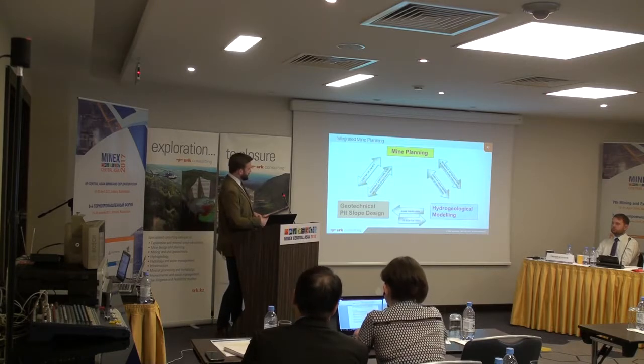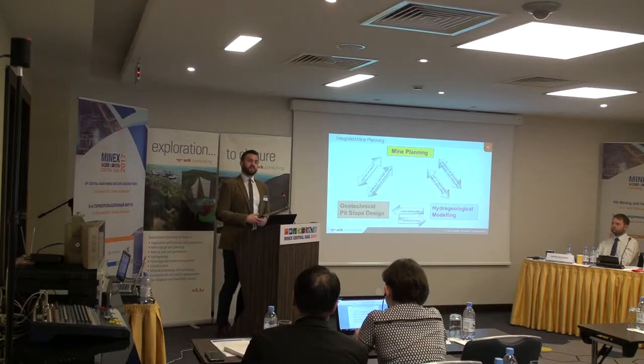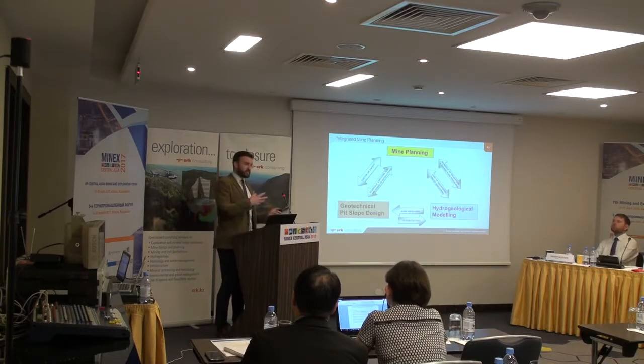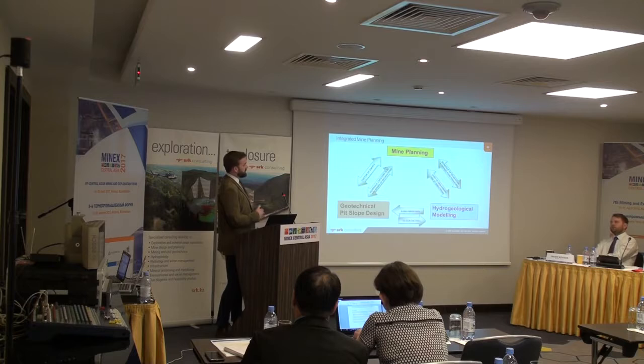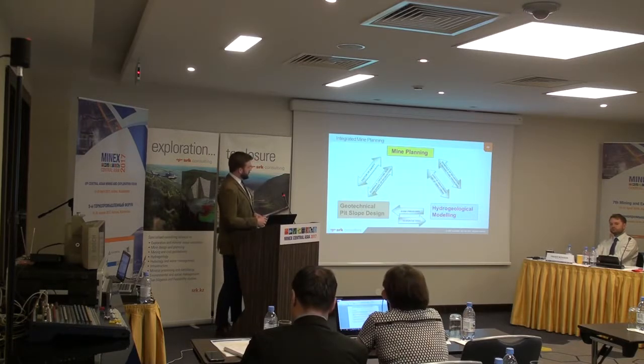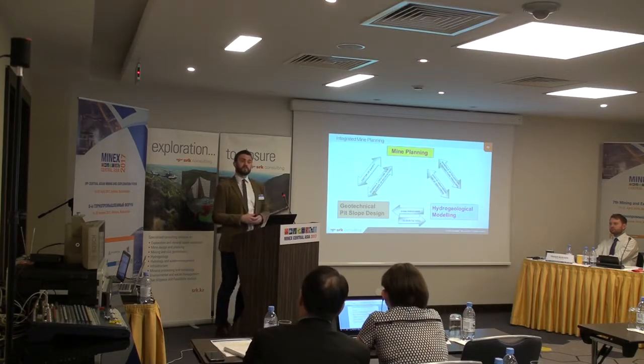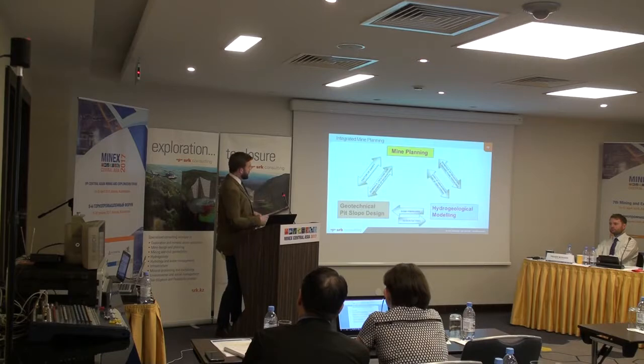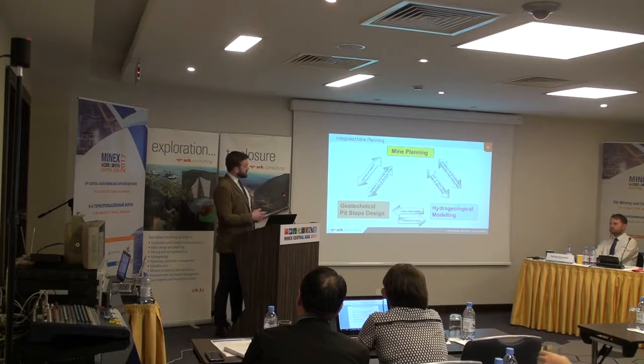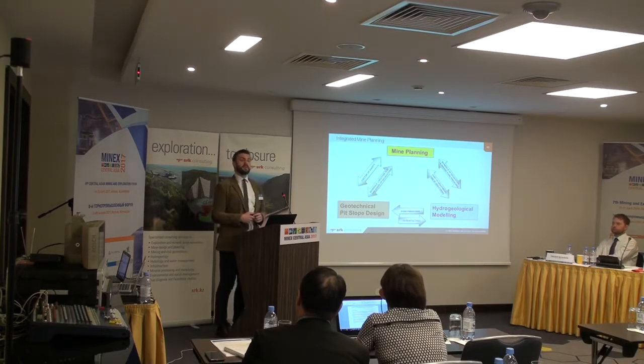These really feed into each other. We need to understand the factors of safety and the probability of failure from the mining engineers, and what kind of risk our clients are willing to accept. We also need the Whittle pit shells that we spoke about earlier from the mining engineers before we start our slope design. They also feed into the hydrogeological modelling, and one of the elements there is the cost and time of dewatering, which needs to feed into the mine planning.